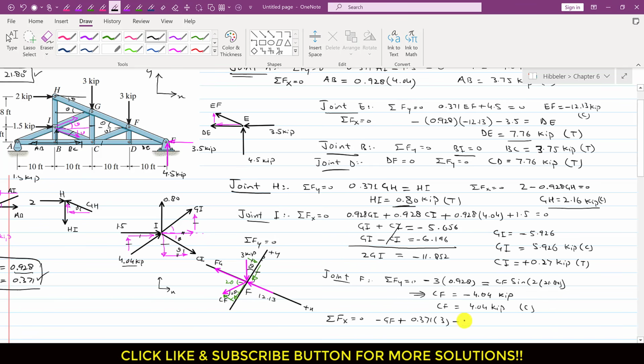CF magnitude is minus 4.04, according to our assumption, so we use this minus value: minus 4.04 cos of 2 theta, and theta is 21.80. Similarly, this 12.13 is also acting in the negative x direction, so I will write minus 12.13, and this is equal to 0. Now we have only one unknown, GF.